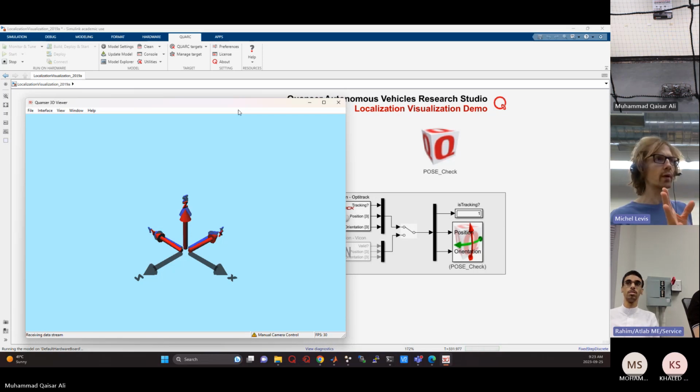4 would work. You need at least 3 cameras to view the drone at each time. If you only have 4, that's pretty tight. You might be wanting to cut costs, but if you only have 4 cameras and you need 3, that means the drone will be losing tracking pretty often. So 6 is better, more robust.